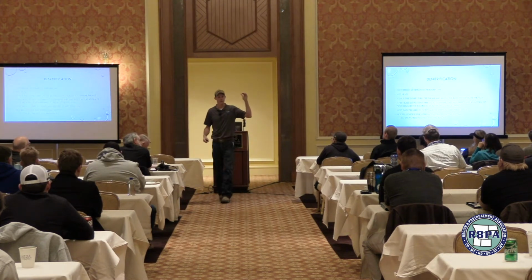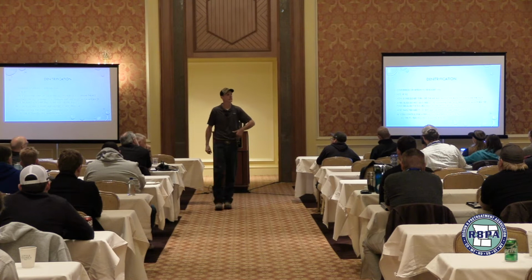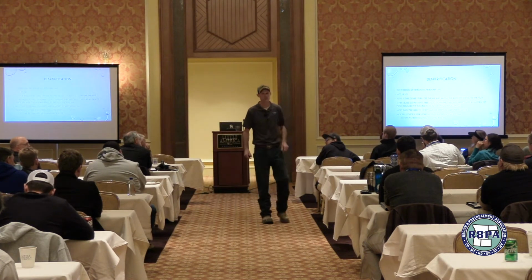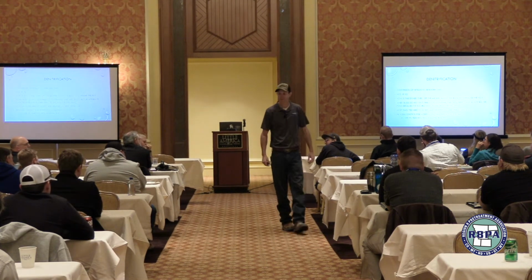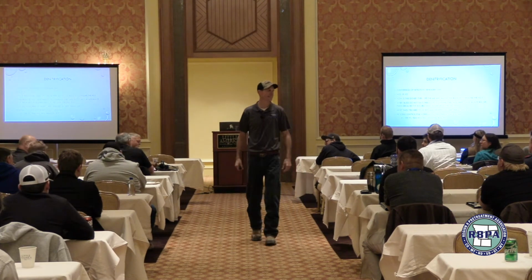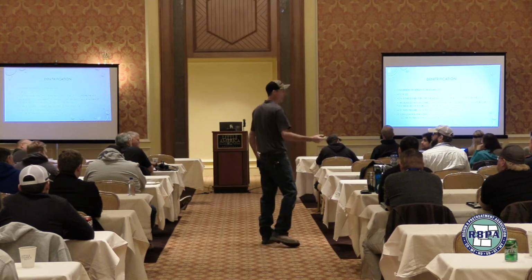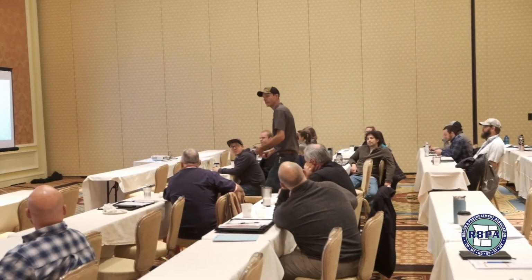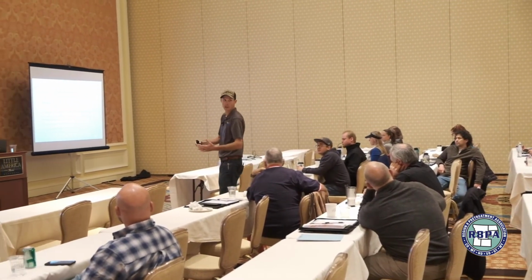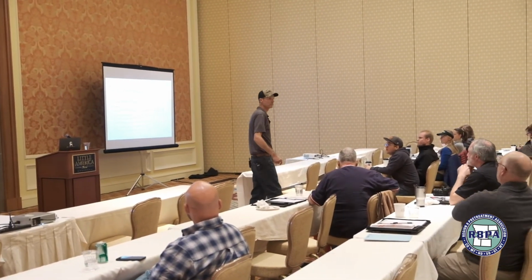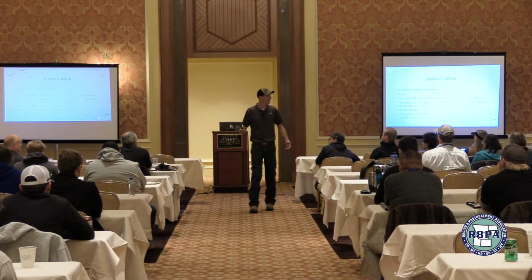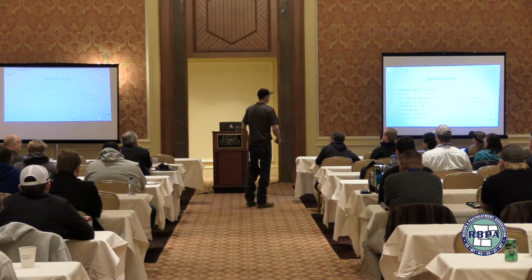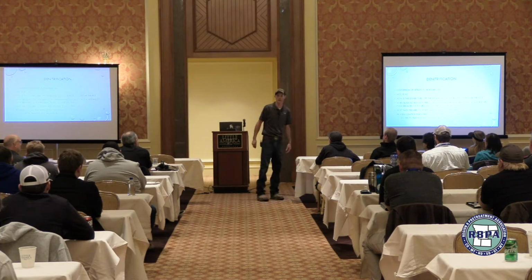Now, if you run your ORP down to negative 250, negative 350, what happens? Fermentation. What happens with fermentation? We produce volatile fatty acids. So now the simple way to do that would just be to dump our grease interceptors into the wastewater plant, right? Instead of creating VFAs for my other bugs to do work, just dump grease traps into them. Simple, right? Not even close. You dump a grease trap into the front of your A basin, you got more problems than VFAs. You probably ought to be looking for a new job.